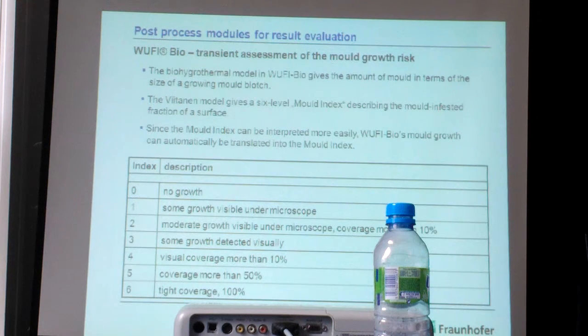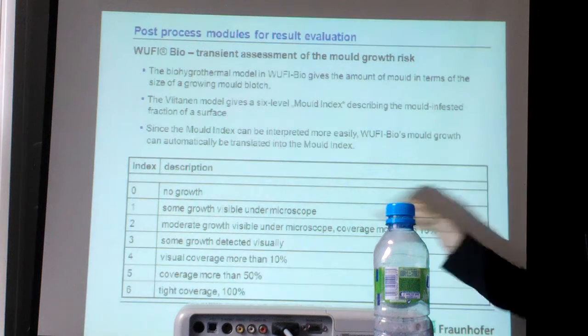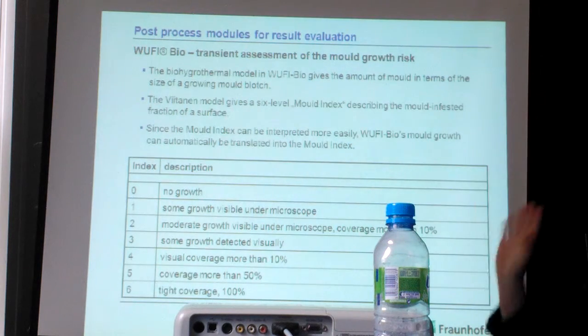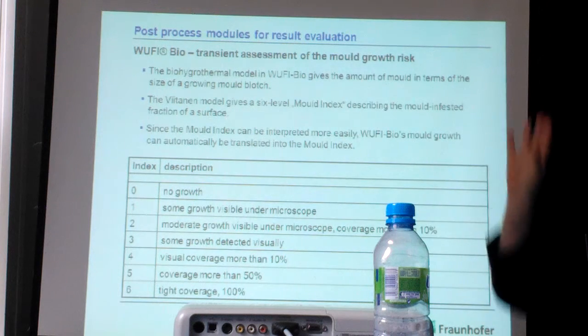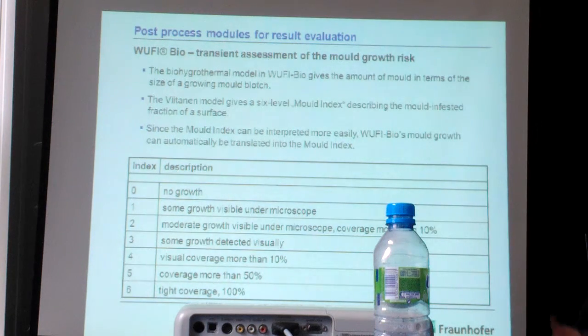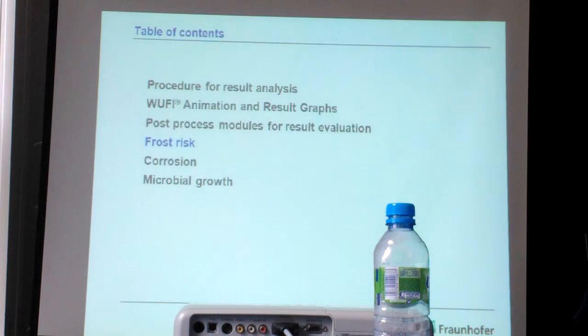But you also make sure that you've stripped off the wallpaper glue, preferably if you can, the gypsum. You know the different isopleths, the different limiting curves. You make sure that you're in the highest curve, not the middle curve, by preparing the wall. You might be putting on an alkaline or biocidal wash, which is available from lots of suppliers, and can be sprayed on or painted. Literally lime wash. There's all sorts of different things you can do to inhibit the mold and reduce the risk of mold, reducing the space so you're tightly bonding and you've fully grouted the surface, the bonding that you're applying. There's lots of different things you can do to make it less and less likely the mold will occur. Obviously, air gaps, sealing and skirting, all those different things help.